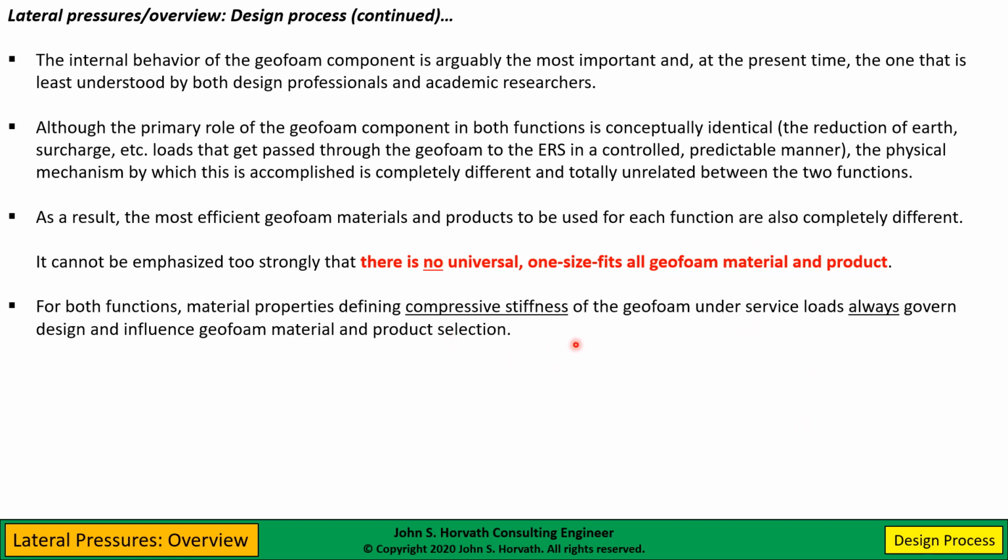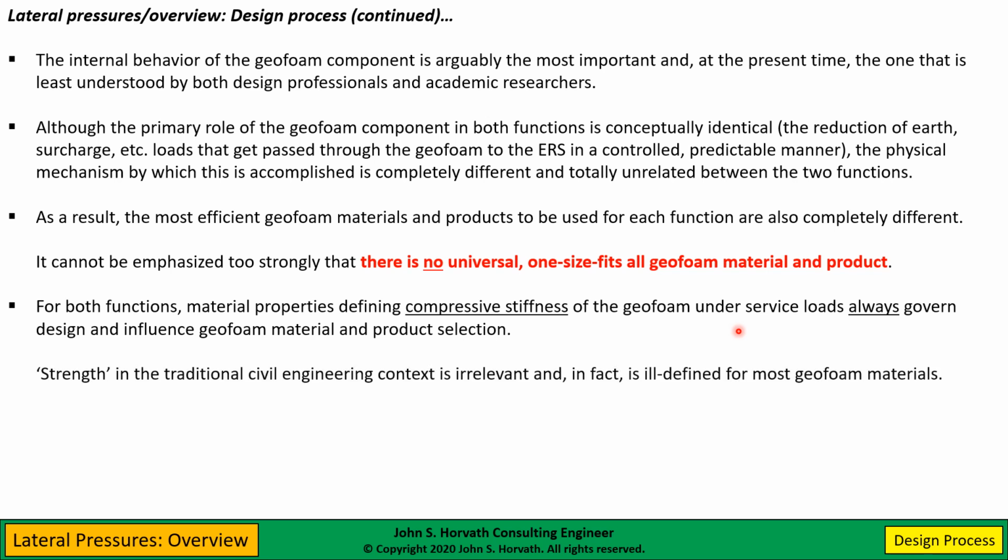Now, regardless of the function, the compressive stiffness of the geofoam under surface loads always governs the design. I emphasize this because, especially now with LRFD, we're really used to thinking in terms of strength of materials. And in fact, strength is irrelevant, not only irrelevant, for most geofoam materials, it's ill-defined.